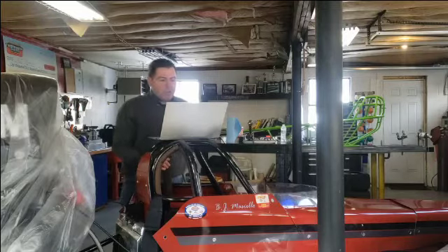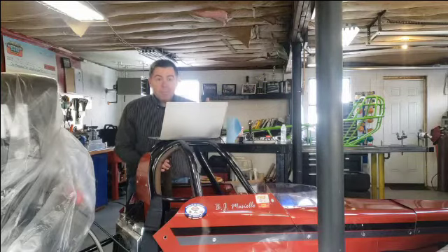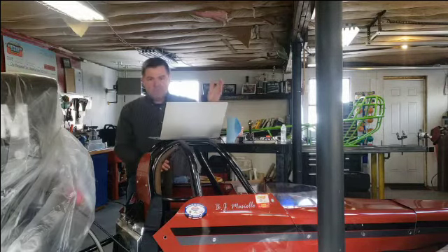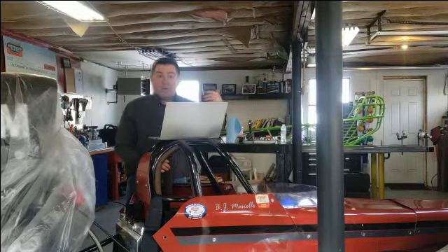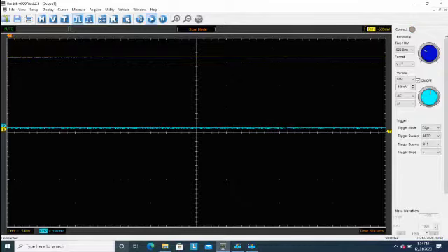So right now, if we look at our screen, we are seeing a reading of approximately 16 volts. So what's going to happen when that fan turns on? Well, as we know, we are going to see our voltage drop, and we're also going to see our current increase, because current is now being drawn, kind of like turning the valve on. Let's watch what happens, and let's talk about why this happens in the way that it does.